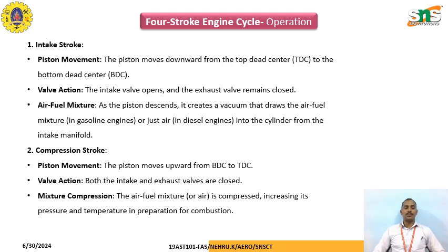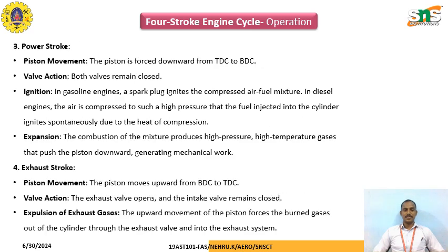Compression stroke: the piston moves upward from the bottom dead center to the top dead center. Both the intake and exhaust valves are closed. The air-fuel mixture is compressed, increasing the pressure and temperature, and is prepared for combustion.